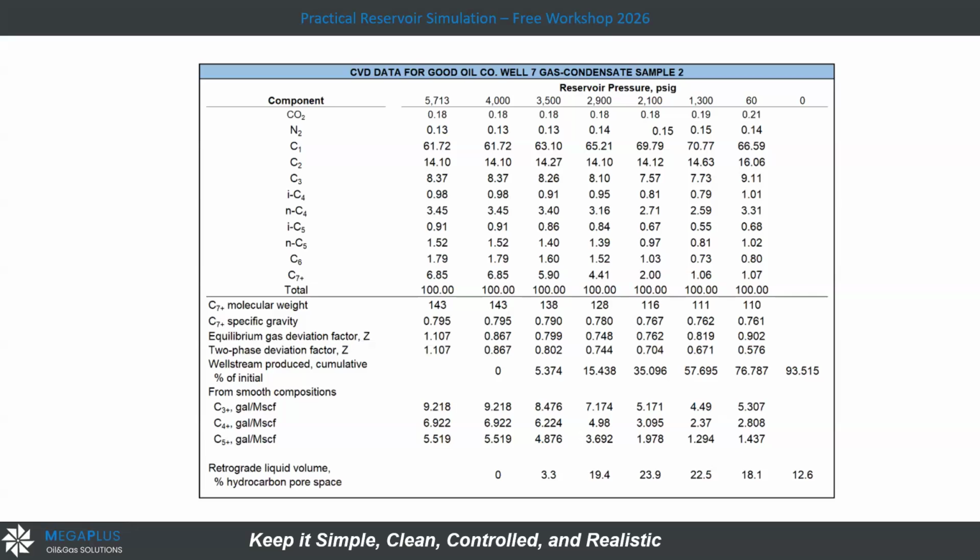As an example, I have from C1 to C5 mole percentage summation, say 70%. And from C6 to C7, which is maybe liquid phase at that pressure, if I said from C1 to C5 it will be 60, then it will be 40. So here I notice that for the hydrocarbon, I have 40% oil and 60% gas. For the water, it's about the volume, it's not about the components. So I hope that I simplified.